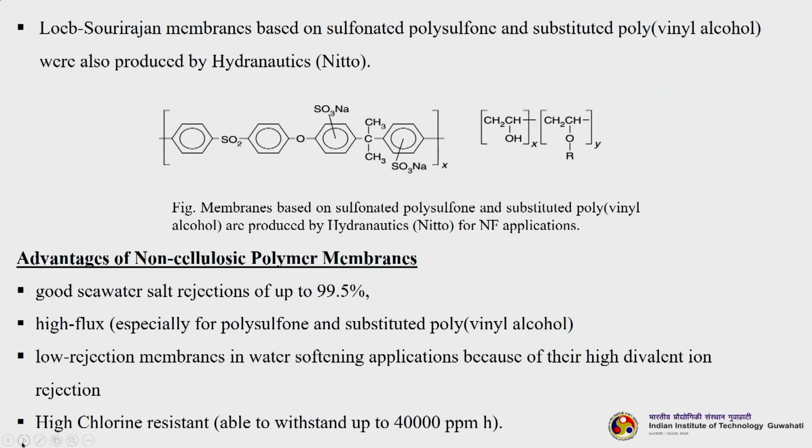Loeb-Sourirajan based membranes based on sulfonated polysulfone and substituted polyvinyl alcohol were also produced by Hydranautics. That is the Nitto brand name. So, these are base membranes based on sulfonated polysulfone. You can see the sulfonated groups here, and substituted polyvinyl alcohol produced by Hydranautics here, but this is for nanofiltration applications.